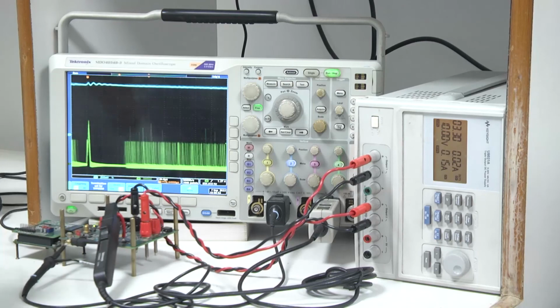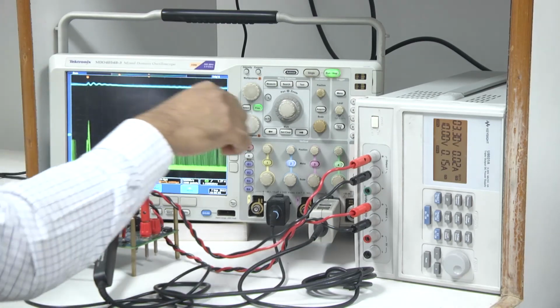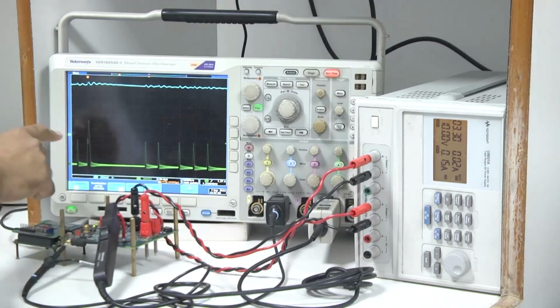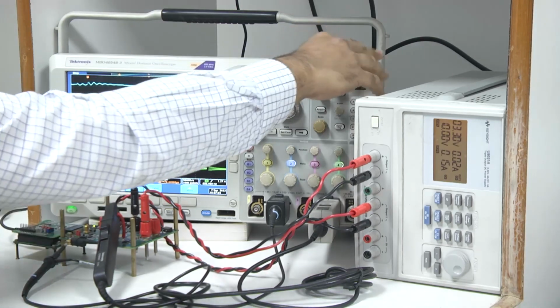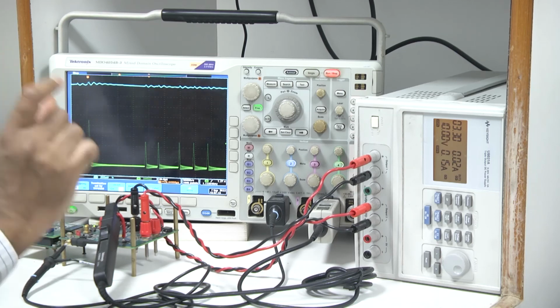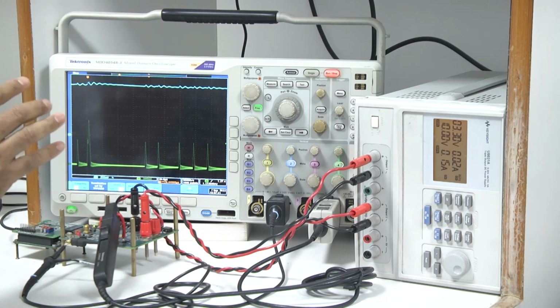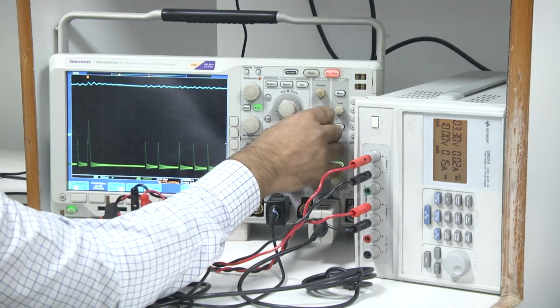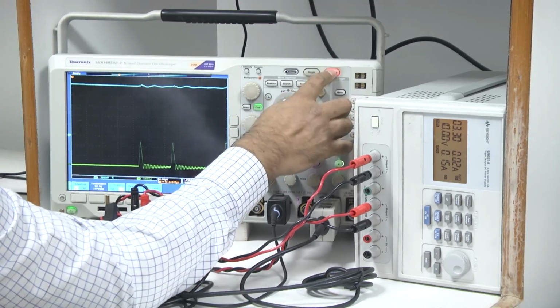If you see the scope, first of all you will find two things here. If we do a single shot, in some cases we are getting two consecutive on pulses, because this depends on the logic. What is the logic here? When the output voltage goes below Vref, we trigger a monoshot timer and it gives a minimum, fixed on time, and we have discussed in this lecture what the duration of the on time is. But now since the input voltage is 3.3 volt, if you zoom this portion, maybe we can continue.